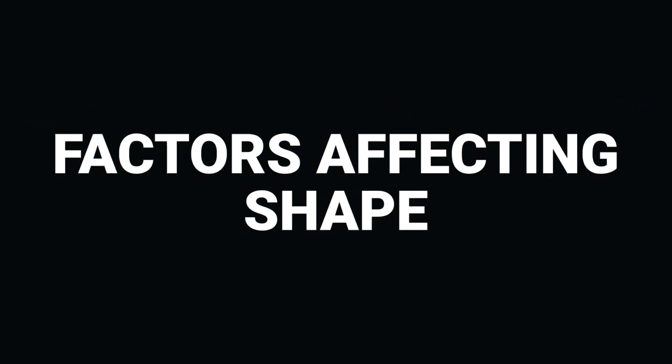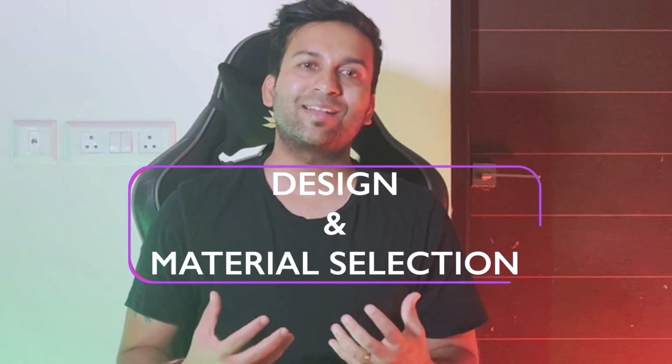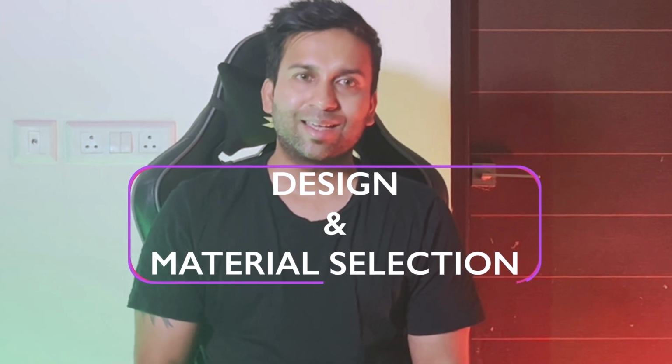Now let's explore the various factors that can influence the shape and position of these curves. Understanding how these factors impact fatigue behavior is crucial for proper design and material selection. First, the inherent composition and microstructure of a material plays a major role in fatigue properties. For instance, if you compare different metals like steel, aluminum, titanium, each will have a distinct SN curve shape and endurance limit based on attributes like crystal structure, grain size, defects, and more.